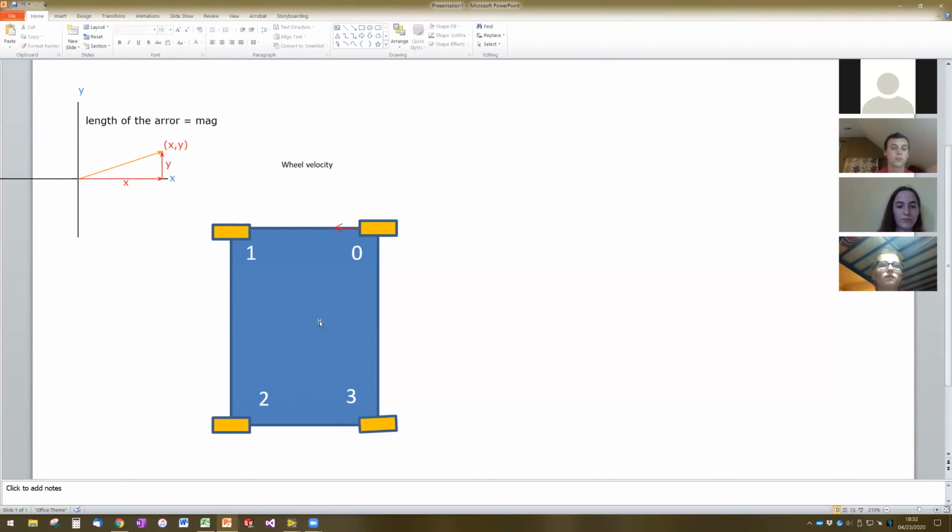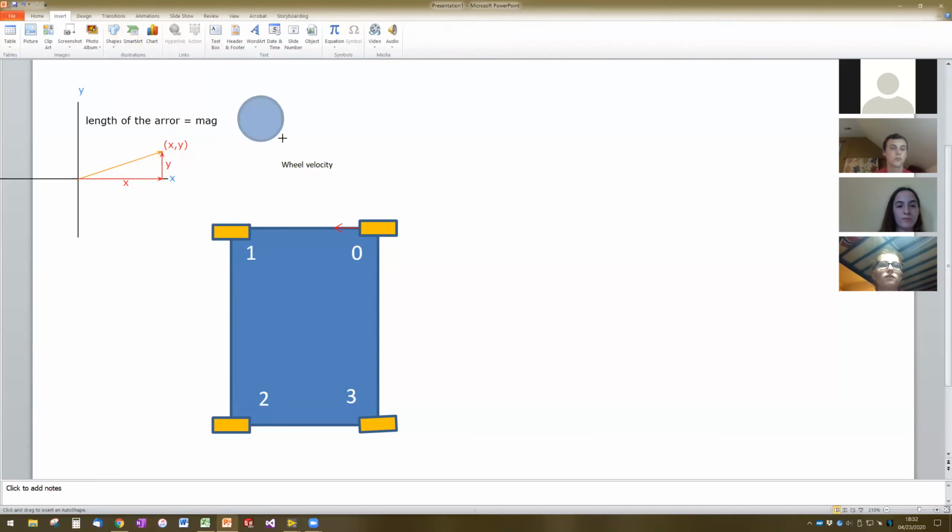So now, we could probably write a pretty simple piece of code that would allow us to do translation of the robot in any direction that we wanted. I mean, really all we need is, if that's our joystick bubble, we look at the angle of where the joystick bubble is pointed, in the XY quadrant of the joystick, and just point the wheels in that direction, and then look at how far the joystick's been pressed in order to know the wheel speed.